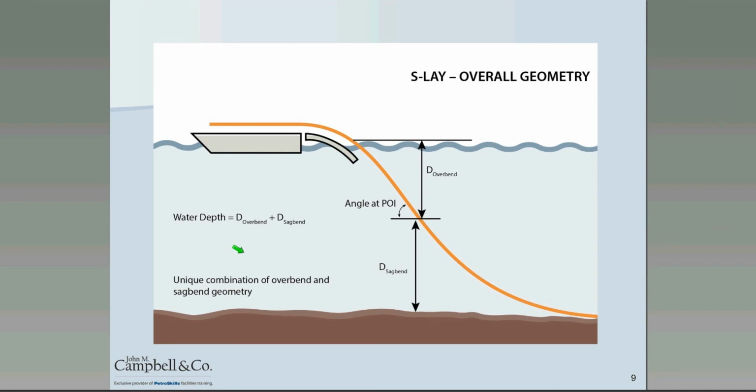The biggest difference is the vertical offset that you go through. For an offshore pipelay operation, it's maybe hundreds of feet in terms of depth, maybe even thousands of feet in some of the real deep pipelay, whereas for an onshore configuration, you'd be a few tens of feet at most, and a quite common number would be a total vertical drop of the pipe from where it's been welded to where it rests in the bottom of the trench of about 10 to 12 feet.